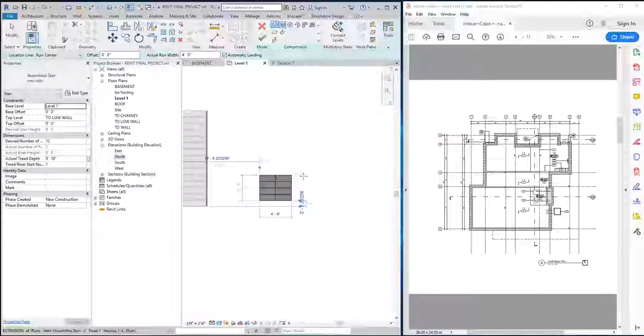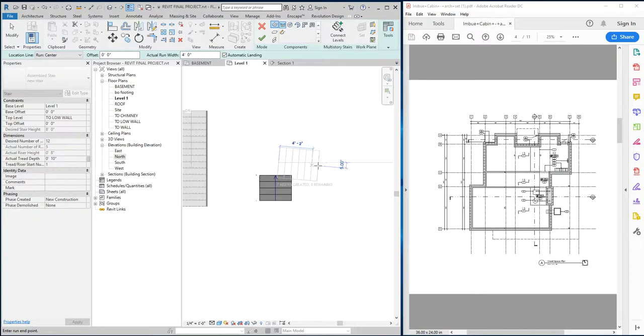The way that the landing is generated is that I generate a few stairs, and then whichever direction my stair is turning, I sort of move in that direction. But I have to be careful about how I think about the landing. If I choose here, click, you see the landing doesn't form because there's not enough space for it to form, right? If I choose here, click, you see how my stair is not outside this edge of the original stair. So if the stair is coming in perpendicular to that, I get a really crazy looking landing.